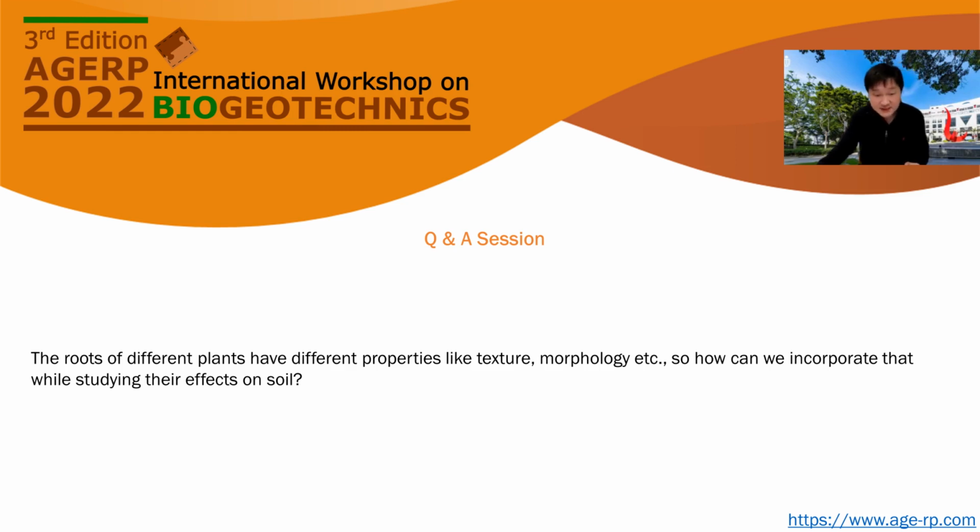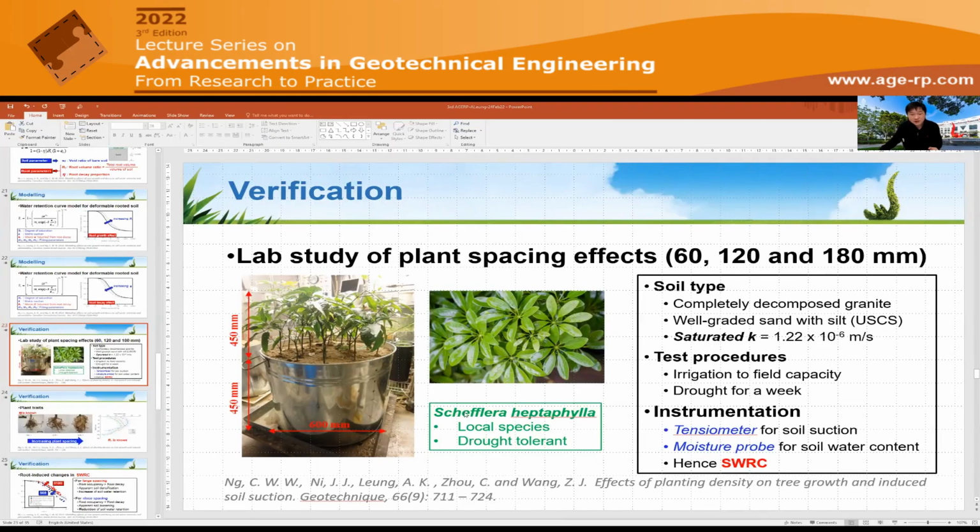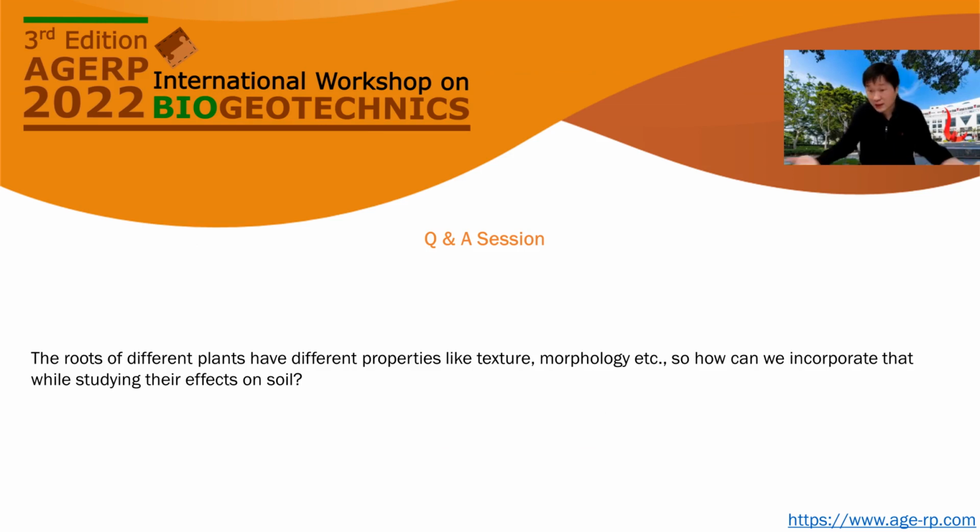Let me see. Okay, so this slide. Yeah. So we have to identify the correct sort of ecological engineer from a landscape perspective first. So once we agree that the species is appropriate for landscape, first of all, and then secondly, we have sufficiently convincing root morphology, then we elaborate our investigation. Otherwise, if you select some shallow-rooted species, it's no use for slope stabilization purposes.